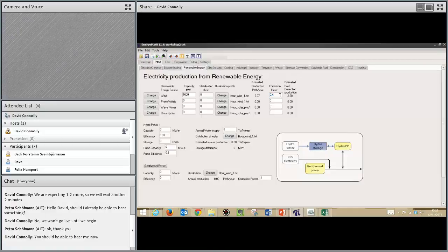And I just want to do this because the capacity factor of our wind turbines is going to have a big impact on the benefits from our large-scale heat pumps that we analyze later on in this demonstration. So I just want to make sure that the capacity factor is at a reasonable level. So now we have 1,000 megawatts of wind produces around 2.7 terawatt hours. So approximately 7,000 megawatts produces almost 20 terawatt hours, which is the electricity demand that I have.